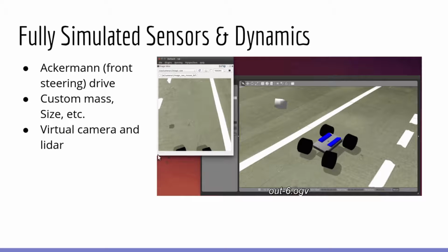And so here we can see a close-up example of that car that was running in the simulation earlier. We have a camera here that's outputting data on a camera stream that is consumed via ROS. And if you notice, this GUI is actually the same one that we would use for a real webcam or real camera. It's just subscribing to an image topic, and the software can run on either one. We can also see as the vehicle moves around a bit, even as the wheels just turn, the friction forces are all kind of shuffling around the robot, and all these things are working into how this robot is simulated.